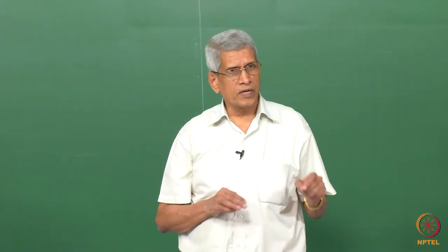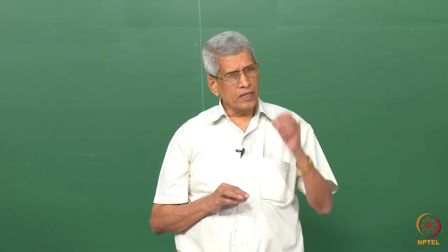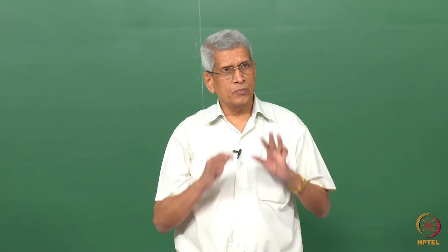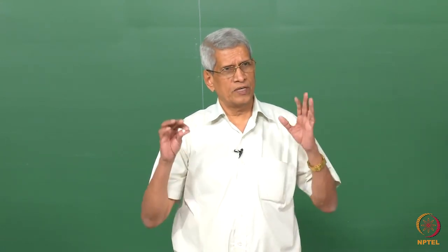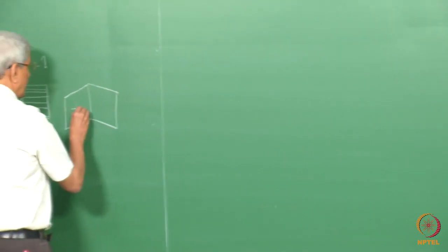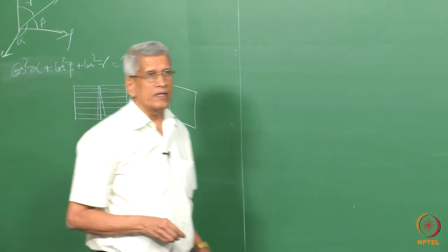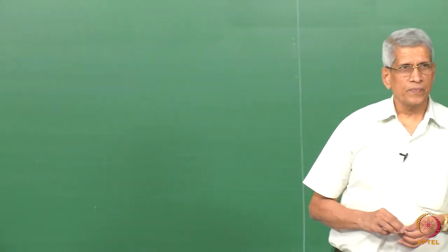What is the other important characteristic whenever we consider a grain boundary? Another important aspect is that if we assume these boundaries are made with dislocations, generally we know that when dislocations are present, there are long range stresses. If a dislocation is present here, the displacement field will be there all over. The long range elastic stress is there over large distances.